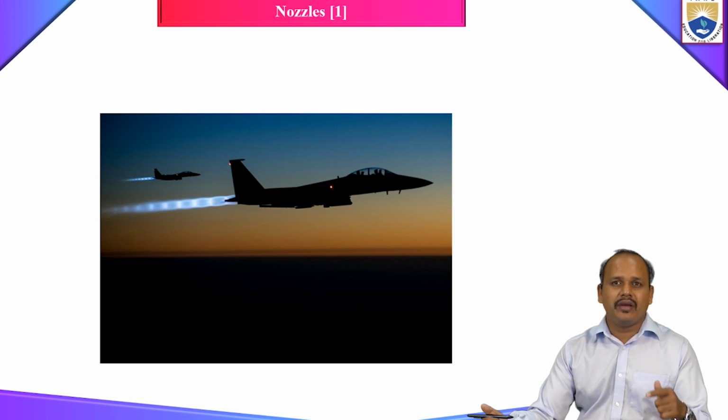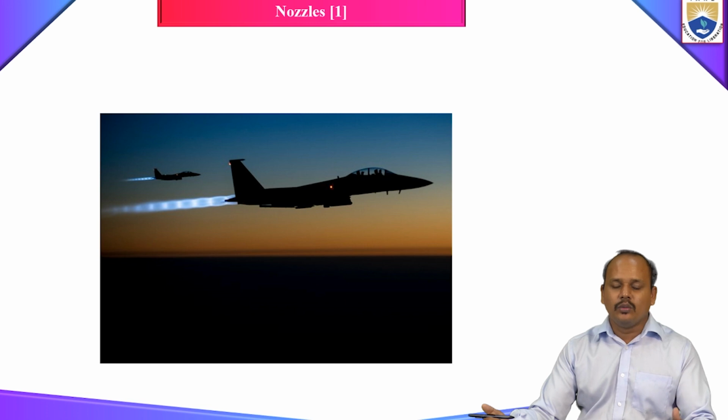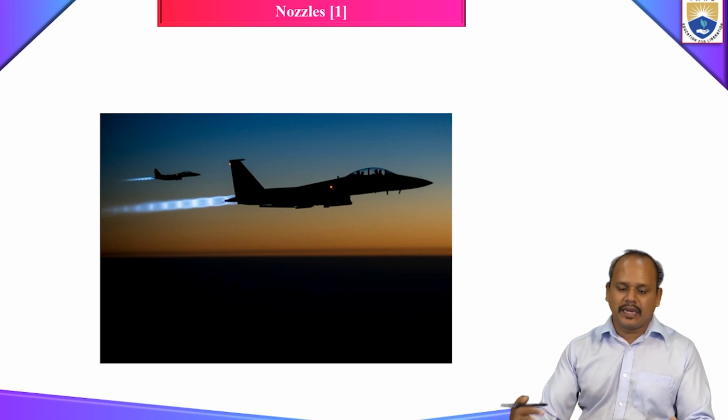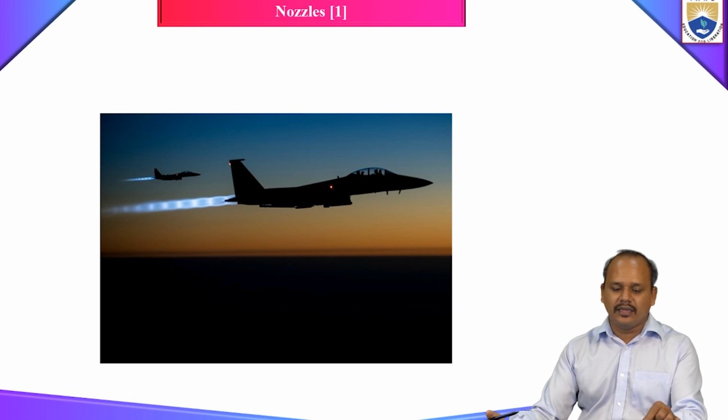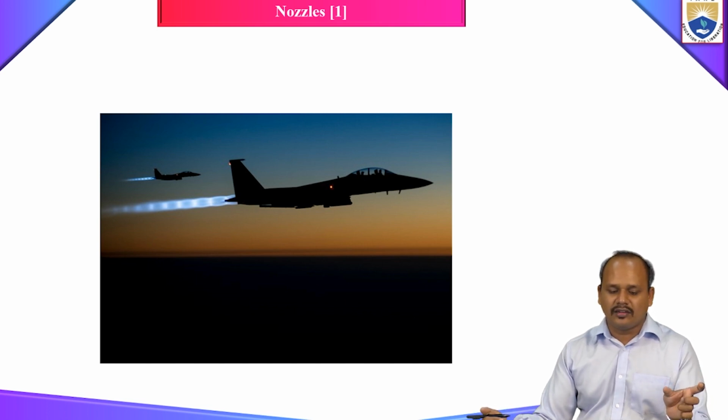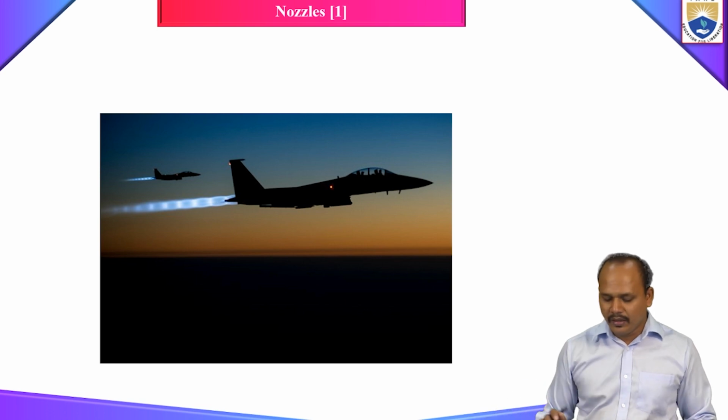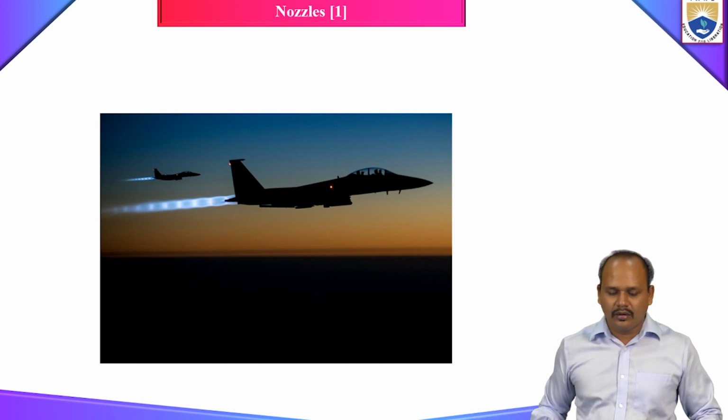So it is very, very important to understand the operating condition so that we can introduce a mechanism to increase the mixing of the flow coming out of your nozzle with the surroundings. So I can have a lesser number of shock cells. Lesser shock cells means what? You will have less noise generated in this case. That's why it is important to know the operating conditions of our nozzle.